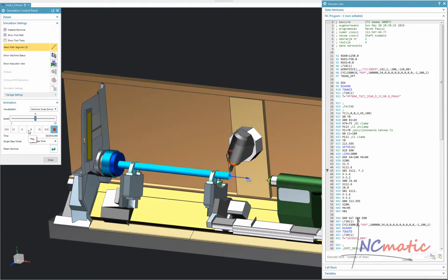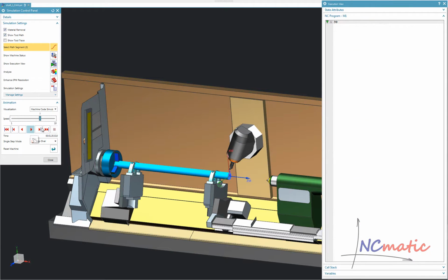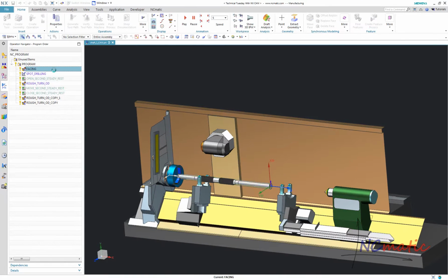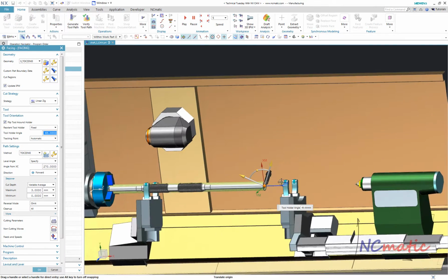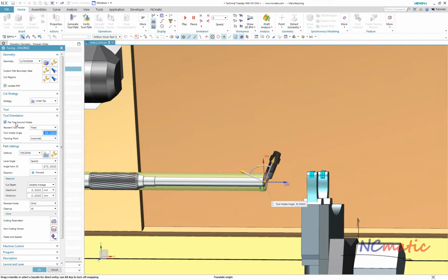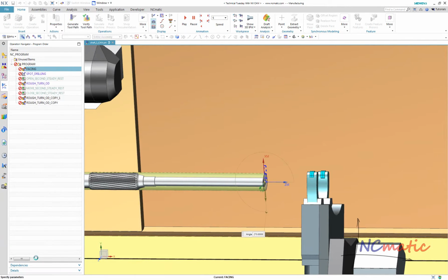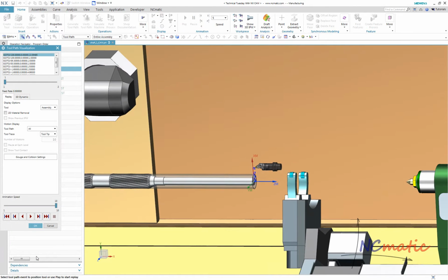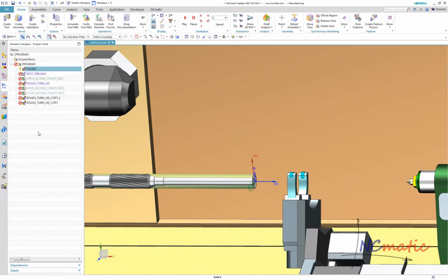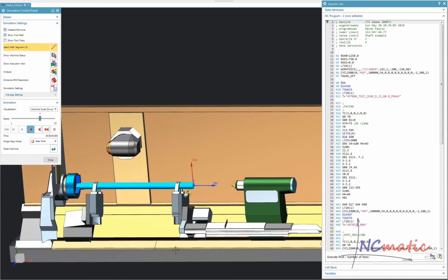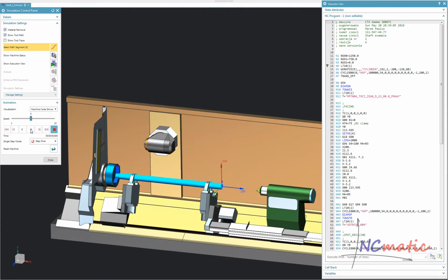The first operation is facing. Notice how the head is oriented. Let's assume that I prefer to do this facing with the tool in horizontal position. To achieve this, all I need is to change the B-axis angle and rotate the tool around its axis. In NX, it is called flip tool around holder. After this modification, you will see why it is important to use ISV.